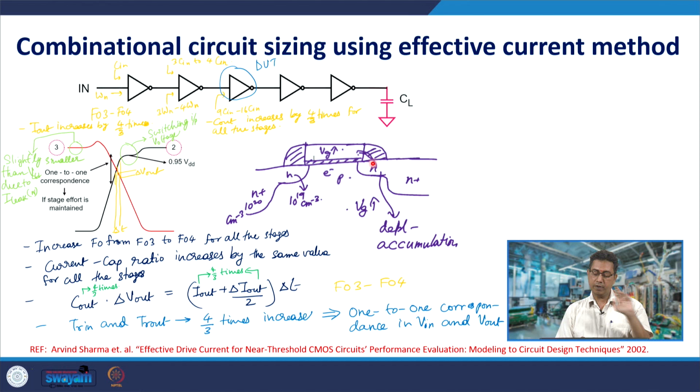The LDD, because of the work function difference, is either depleted, or as you increase the gate voltage, the depletion region in the channel would increase, and in the LDD you would go towards accumulation. Once it goes from depletion into accumulation, because of this fringing field, you would observe a sudden increase in capacitance, because in accumulation the capacitance is quite large.